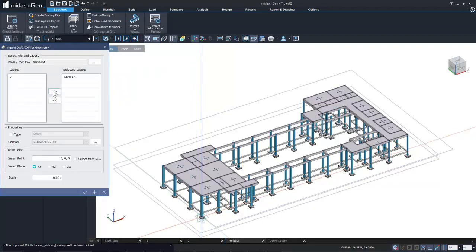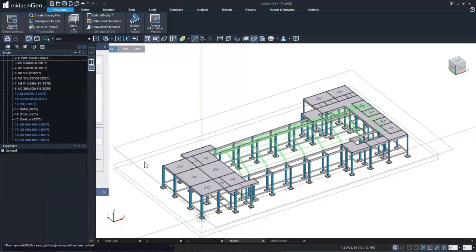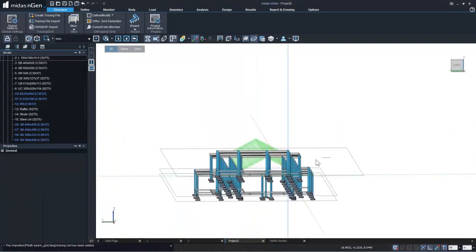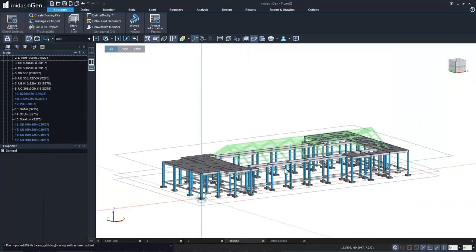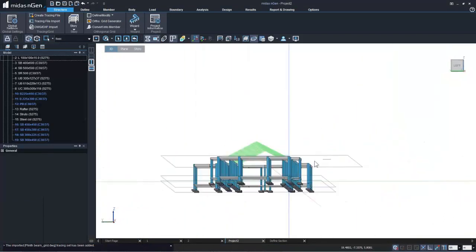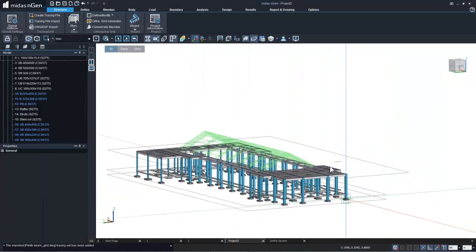Right, this is a 3D type, and this one is having a scale factor of 1. All right, so as you can see over here, a preview of the steel truss, and all I need to do now is click on OK. So here we have our sketch. It's not member. We have to still use or convert this sketch into members.